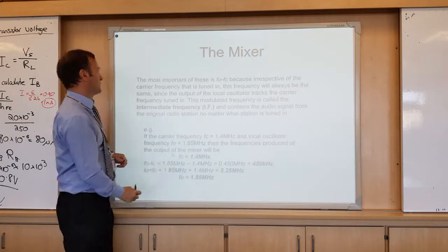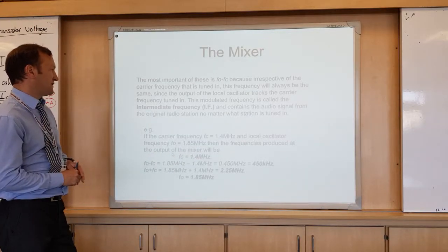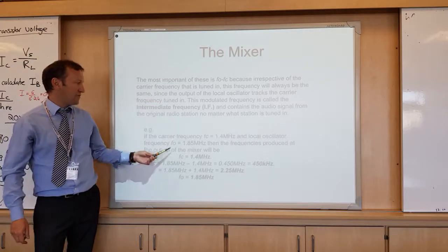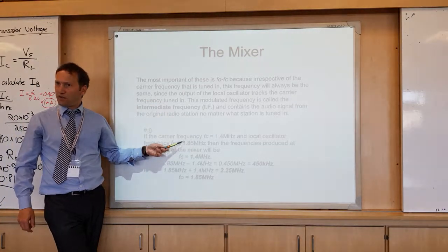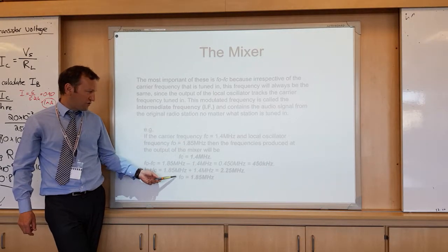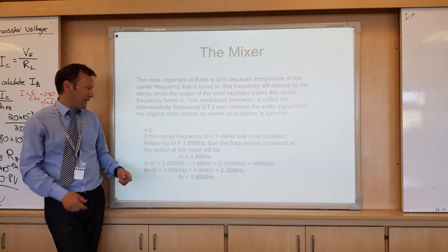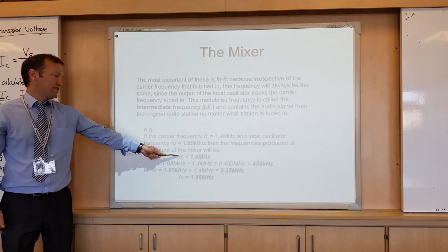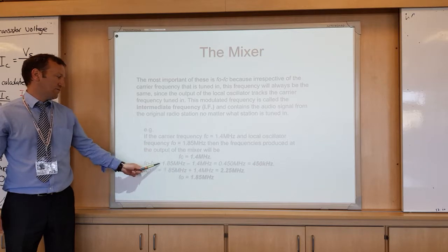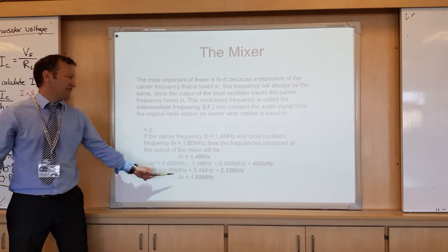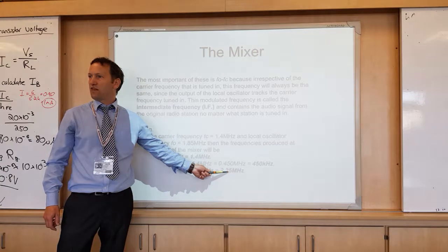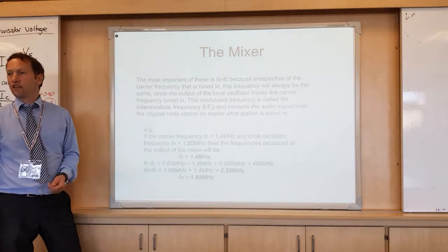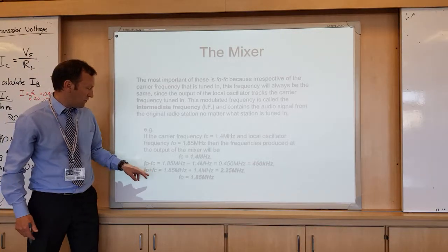That means the intermediate frequency, which we sometimes have to calculate, you have to add them together and work it out. Watch out, it should be around 450 kilohertz for the IF frequency. Carrier frequency, we don't want that. We only want that one. We don't want that because it's an even higher frequency, so it's even harder to mess around with. And the oscillator frequency on its own is pretty useless. It's just a sine wave, so we definitely want that one.